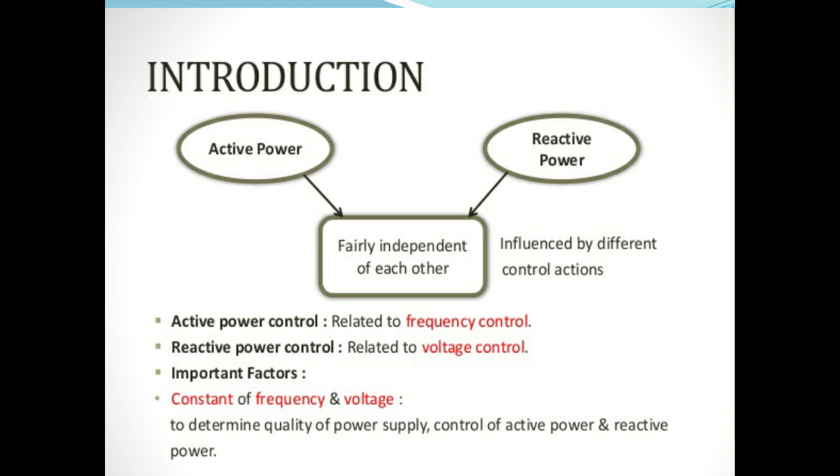Resistive loads are frequency independent and power loss in resistance is equal to I square R, that is independent of frequency. There is no effect of frequency change. For example, light, heater, oven, etc. come under resistive load.